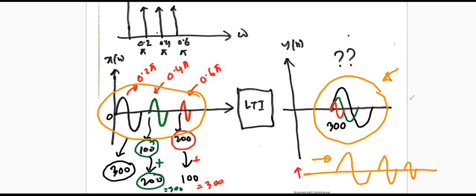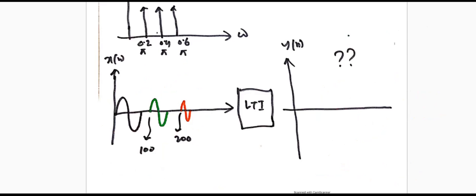Of course, we need to put an all-pass filter in such a way that we can segregate our sequences. We need to put the delays in such a way that the group delays should be equal, whatever the number is. That is how we can solve this problem.